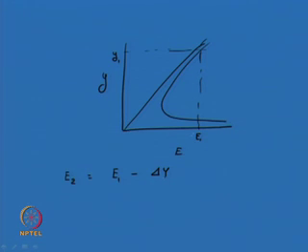Keeping this in mind, from this graph, you just deduct the amount del y. Say if it is something around here, then this is your specific energy E2. Extend it into the graph and you will get your corresponding depth of flow Y2.